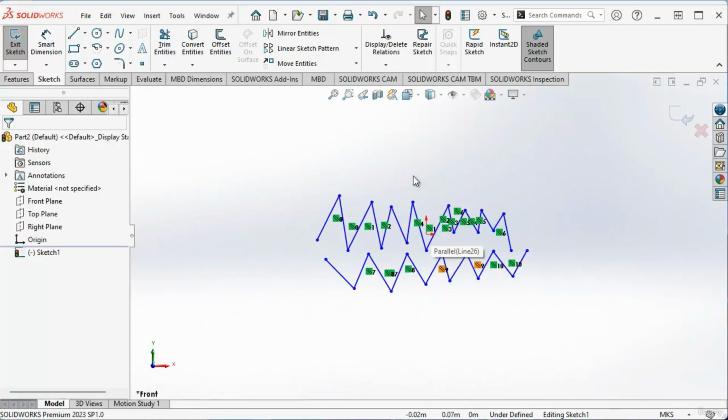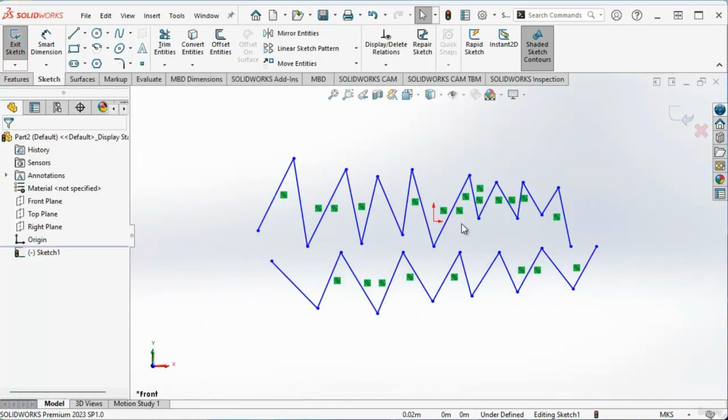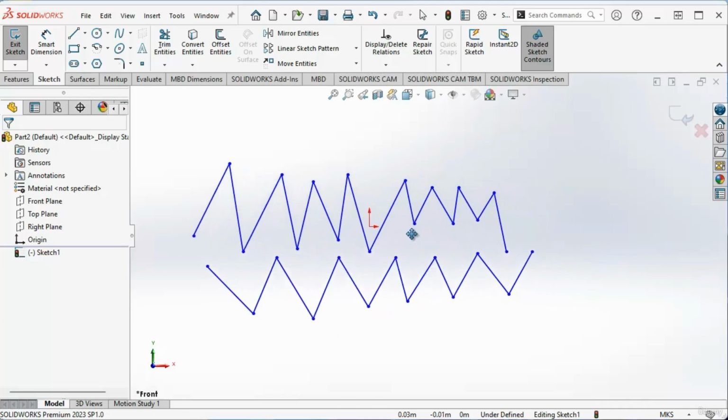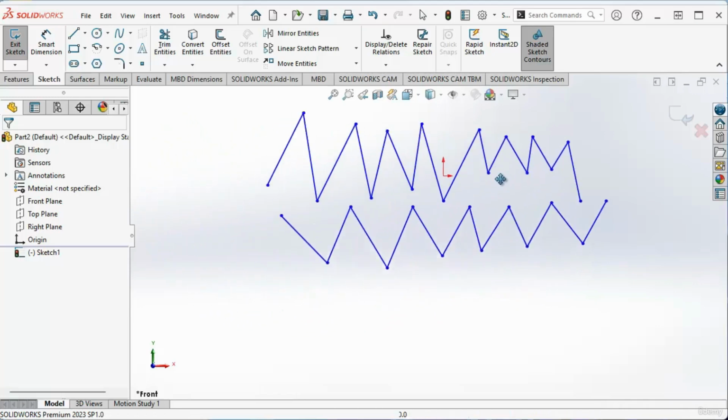So it's your wish. Now if you see, this is the coordinate system about which we have created these lines. If I want to just move these objects along with the coordinate system on the screen, then I can use the control button on the keyboard, just press and keep it pressed, and press the mouse middle button. Both buttons when you press and then move the mouse, you can see.